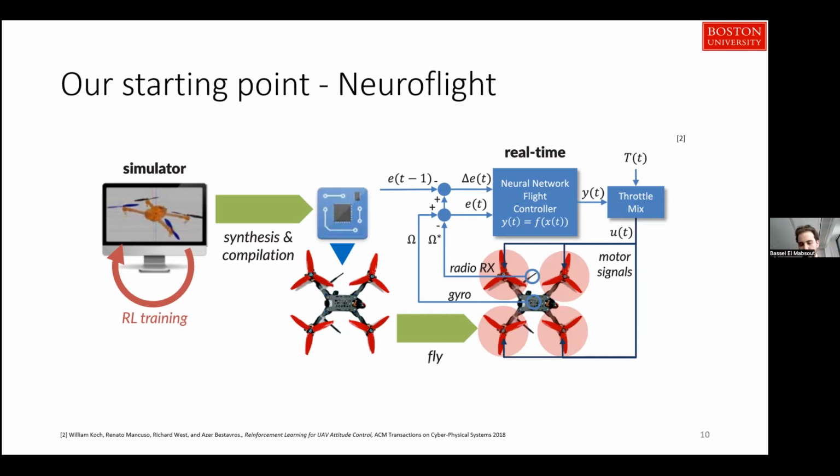It's not an easy control objective because we have 4 motors and we have 6 axes we want to control the quadrotor on. We have X, Y, and Z over the Euclidean space. And we also have roll, pitch, and yaw for the angular velocities we want this thing to reach. So we have 6 channels of control and 4 channels of actuation, which has a specific term in classical control theory, which is that it's an under-actuated system. And it's why it's kind of difficult to control, what makes it non-linear.